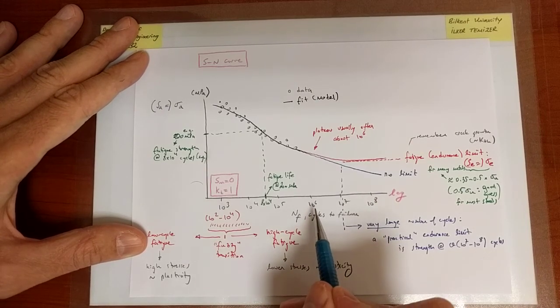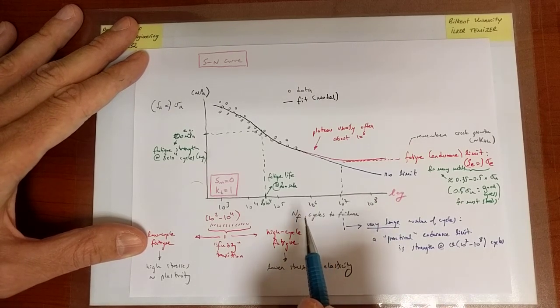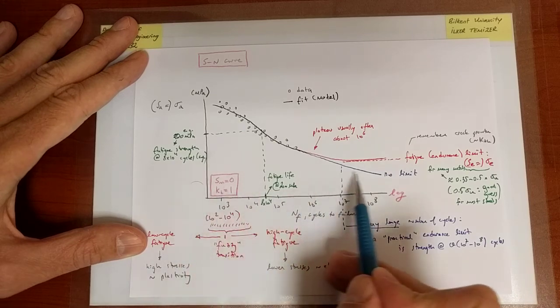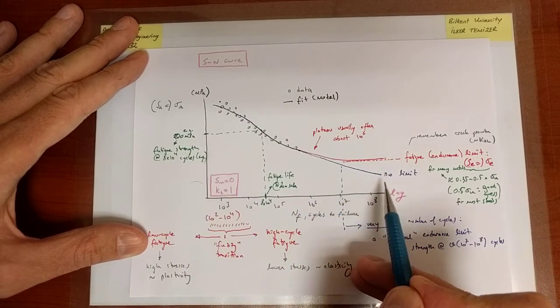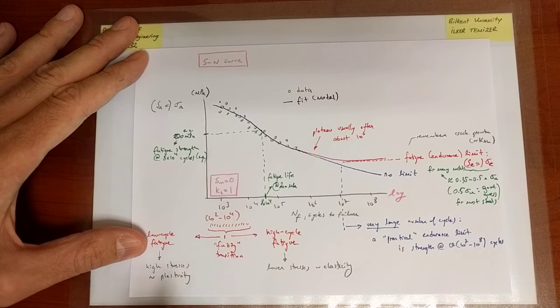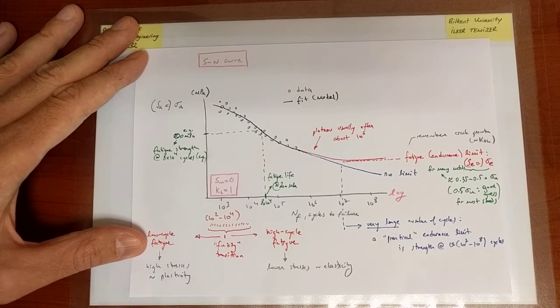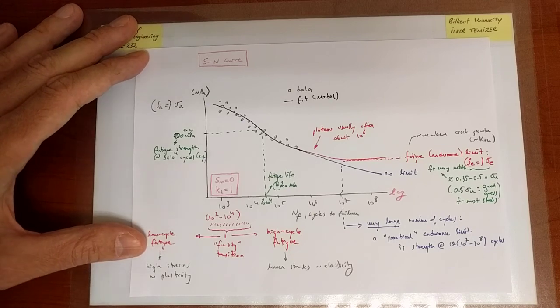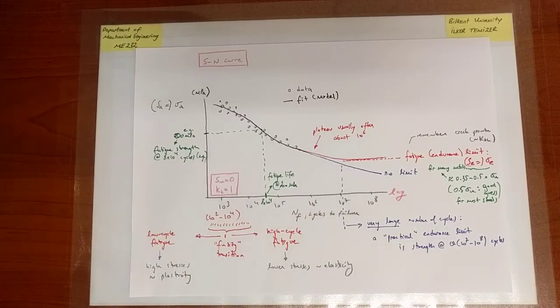So if you really want to make sure that you can do many, many trips and use that car for many years, you'd like to make sure that your stresses are low enough, hopefully below the endurance limit, so fatigue is not going to be an issue. So I need to be able to model the fatigue behavior of the material so that I can design appropriately and achieve the desired lives. Right, so that's the general picture, and now let us therefore talk about design and modeling.